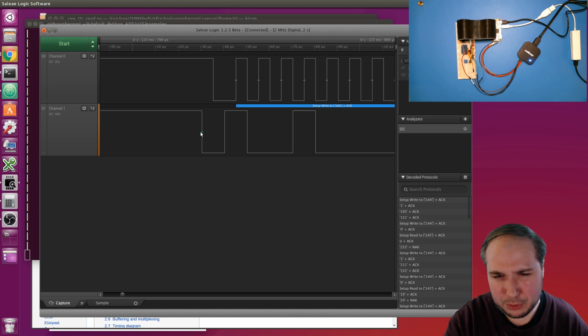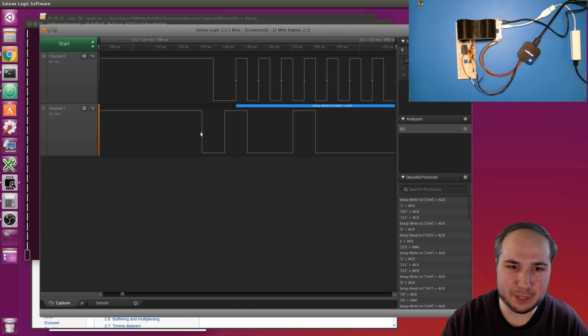Maybe even before we get too far into this digital part of the protocol, one real quick note too on just the physical protocol for I2C. There are these 2 lines. There are pull-up resistors on these lines that will, by default, if nothing is actually using the bus, read at a high signal.